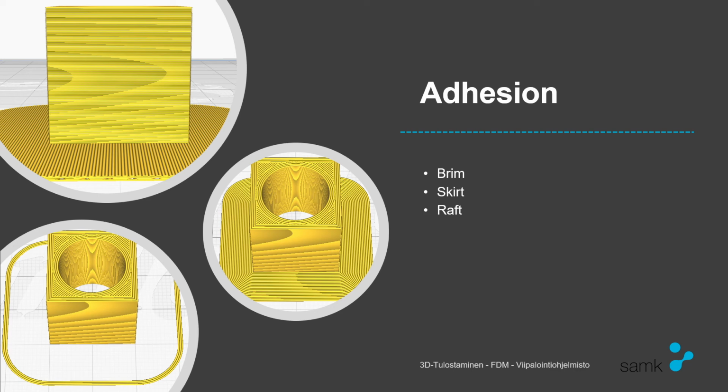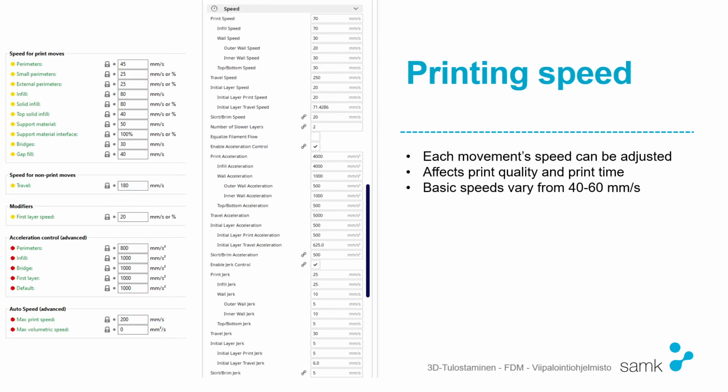This helps out with the adhesion quite a lot, but the raft leaves a bit poorer quality bottom surface, so it doesn't look so good.